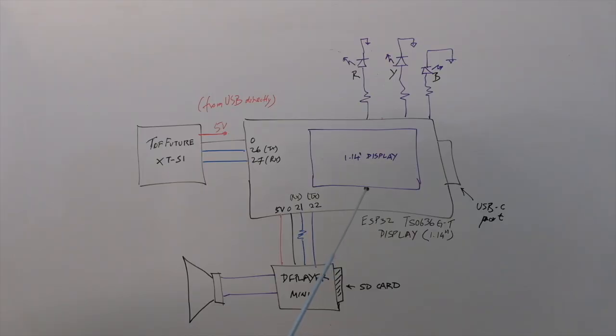Initially I was using the Arduino Nano to develop a simpler version of this, but the Nano is really not powerful enough to handle such more complicated functions, as well as the speed at which it needs to operate. Clock frequency is quite high on this one, so it can do a lot of computation and parallel processing in terms of the IOs and so on.